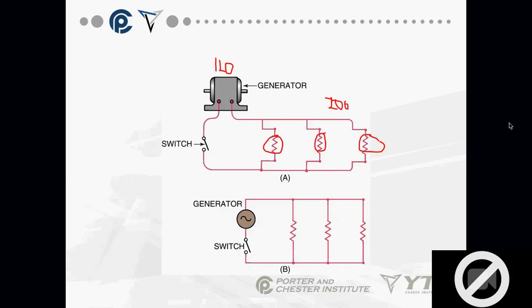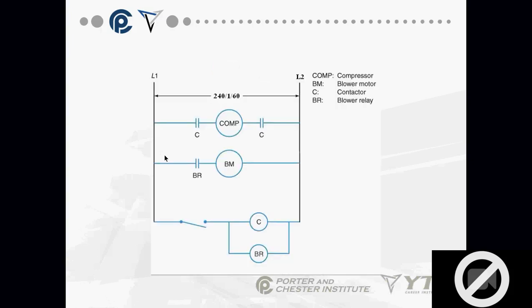The older residences, you may only have 100 amp service coming into it. But that's the total of all the different circuits in the house. So you take a total of everything that's running, and that comes up with your total, and it has to be under the available power. But in parallel circuits, voltage is the same at every load, but amperage adds. Resistance is a crazy math formula that we'll talk about in a minute. So again, let's put it in terms of what we're doing this term.